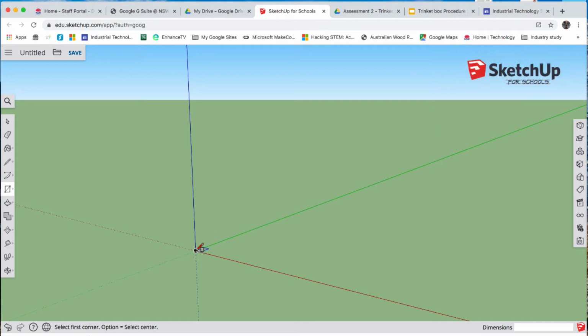Okay, so down in this point here, this is called the origin. I'm going to left click and drag out, so I've got a shape something like this. I'm then going to release, and then I'm just going to type the numbers 220, 220, 12, and then press enter. And you'll see two things. Firstly, you'll see some sort of dark thing appear down there, and you'll see some numbers here as well. This is what I've just typed.